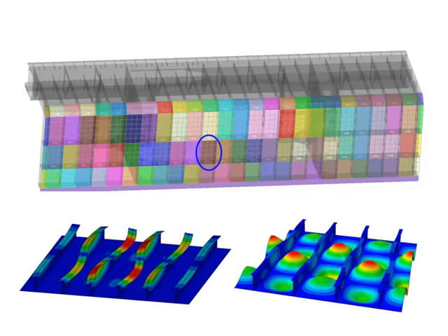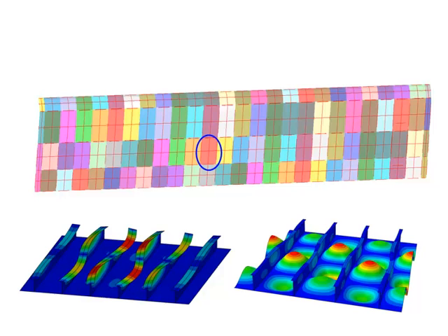For each of these individual panel bays, panel buckling, stiffener tripping, and plate local buckling analyses are performed to all load cases. Hypersizer accomplishes this by first quantifying the length and width of the panel bay spans. During FEM import, these distances are calculated and displayed on the FEM as red markers.